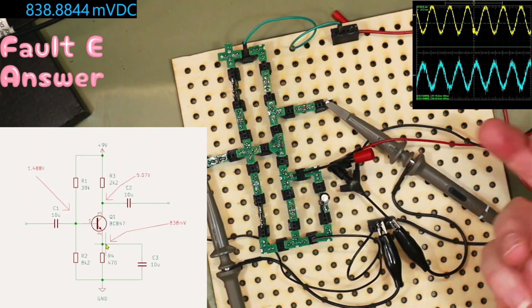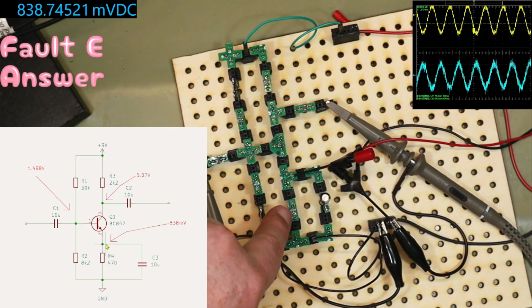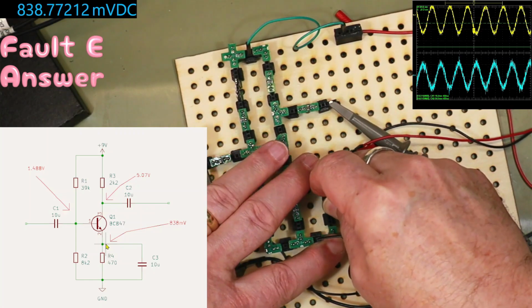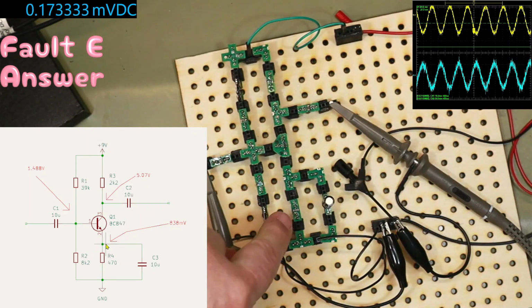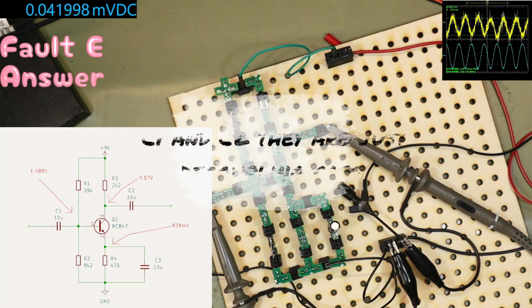So the capacitor is now open circuit. So that resistor is playing part of the gain circuit. Now if we put the capacitor back where it should be, so now the AC is bypassing that resistor. So that was basically all the faults surrounding the components. I won't bother doing these ones.